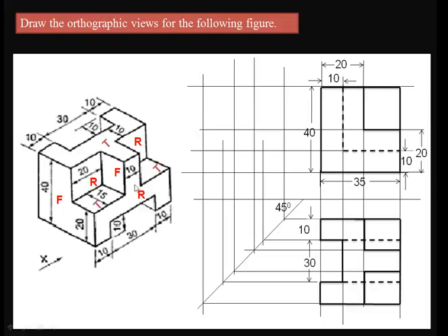So assume here, again analyze the right side view. In the right side view we can see this surface in the shape of a T, or an edge connected to the U shape like this. Similarly we can see this surface and this surface. So totally it will be like a rectangle. Again in that rectangle we can see certain edges. How can we draw those edges? First I would like to show you the two last edges. These two last edges will be continuously visible. Similarly this top edge is also continuously visible as a straight line.